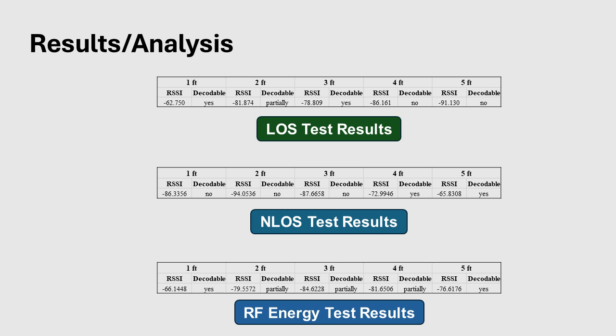For voltage, current, and power consumption, we found our transmitter was able to operate at as little as 300 millivolts and 0.6408 microamps and consumes 0.128 microwatt. For decoding information, we found our transmitter to support data rates up to 1,000 bits per second, mostly due to limitations of our microcontroller.